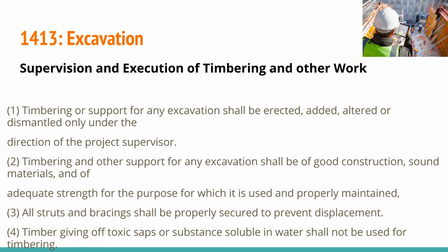Timbering and other support for any excavation shall be good, of sound materials and of adequate strength for the purpose for which it is used, and properly maintained. All struts and bracings shall be properly secured to prevent displacement. Timber giving off toxic sap or substance soluble in water shall not be used for timbering.